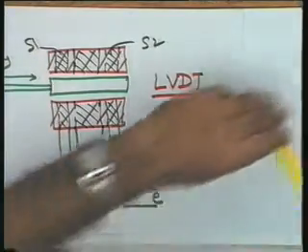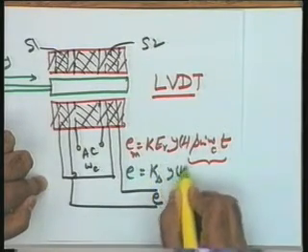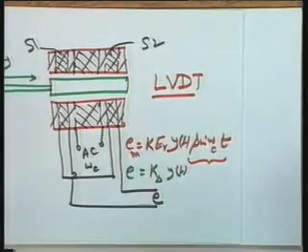signal, and therefore I will be interested in the signal E is equal to Ks into y(t), where Ks is the sensitivity of this device. So the mathematical model for me as far as LVDT is concerned is again only a constant sensitivity, which you should understand is the ratio between the envelope of the output signal and the displacement y of the core. So this part should be very clear, and I am sure when I take the complete block diagram, the flow of the modulated signal and the flow of the signal, the envelope part after demodulation is carried out, will become very clear. Okay?